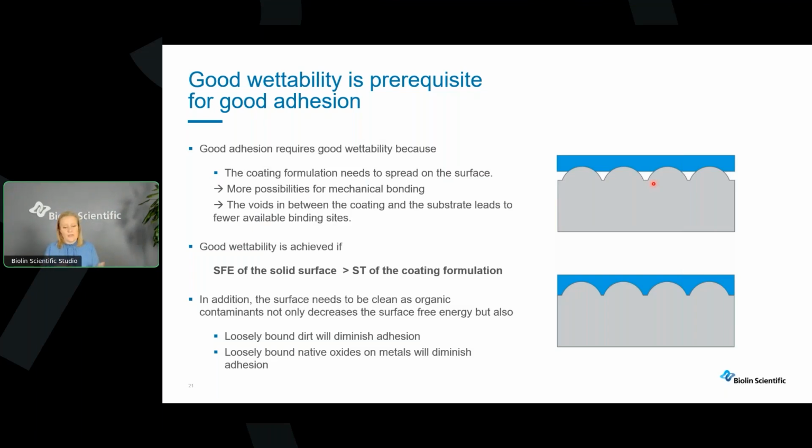And surface free energy is linked here because basically the surface free energy of the solid should always be higher than the surface tension of the coating formulation. So this is how we achieve good wettability.